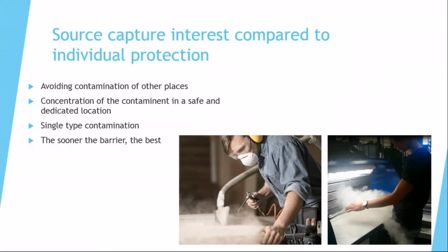So here we have a small comparison between the two methods. With captation at source, you won't contaminate other places of the plants. You will concentrate the contaminants in a safe and dedicated location, avoiding mixing various contaminants together and generating a higher risk of explosion or fire.